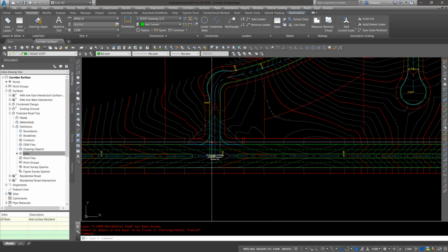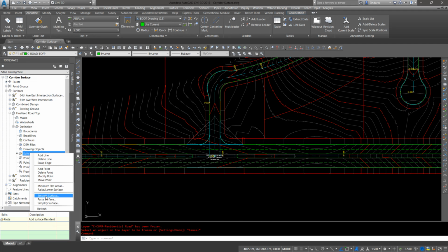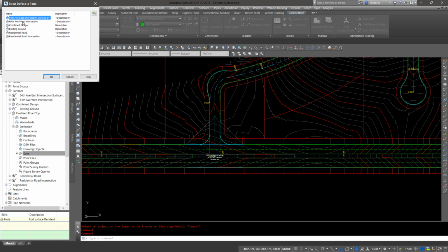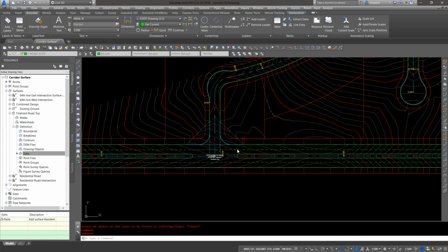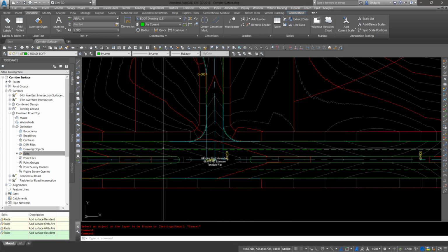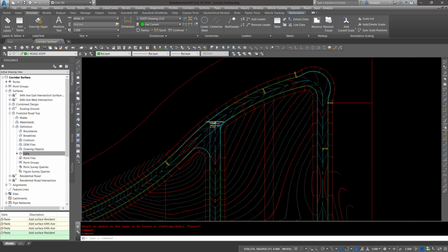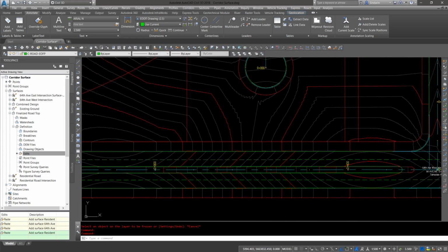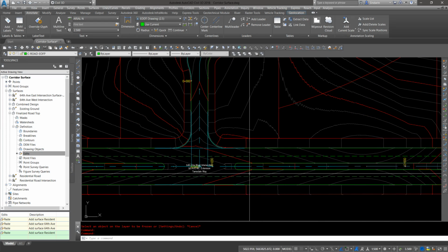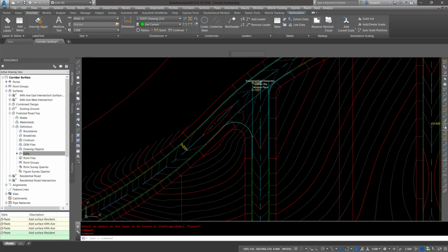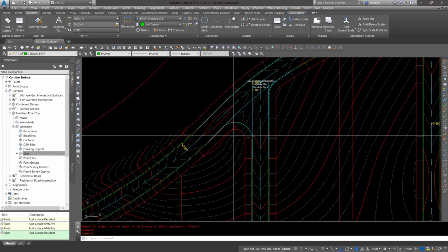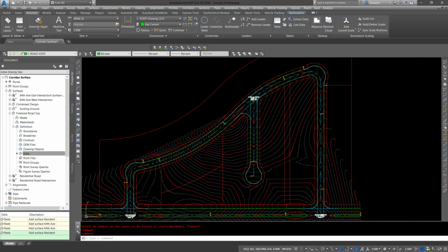As you can see, there's some wonkiness going on in the intersection here, but we'll take care of that by pasting in our west intersection, our east intersection, and our road intersection. So again, I forgot to rename one of them. So we'll hit OK. And we see that's cleaned up the contour lines and it's now a nice smooth transition. Except up in here. So in another video, we'll go through how to fix some of these little surface issues, how to pull this median back. We'll go through how to fix what Civil 3D has done with the corridor up in this spot.